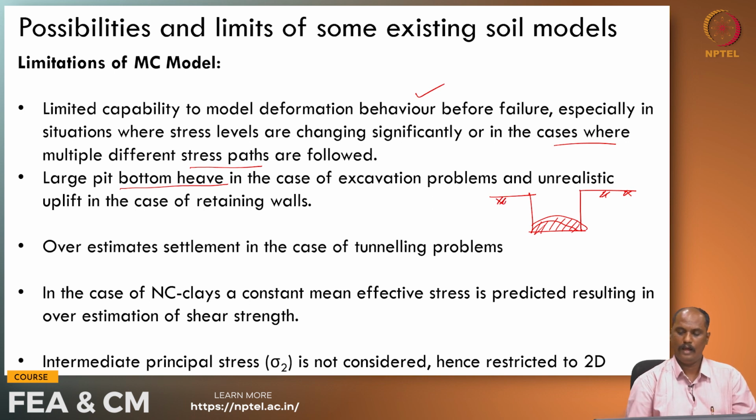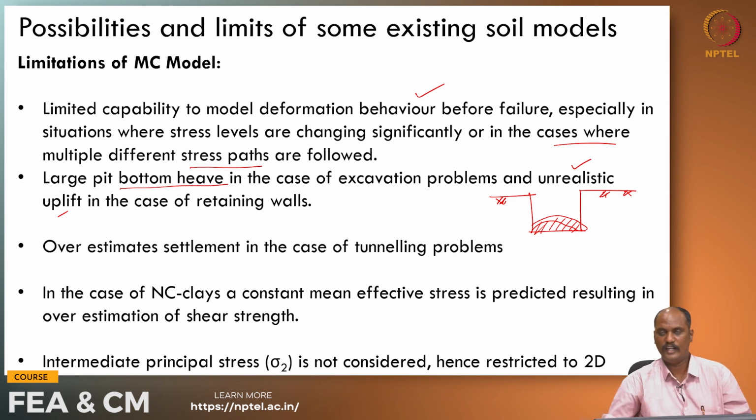You also encounter unrealistic uplift in the case of retaining walls. This is again a problem with the Mohr-Coulomb model. When it comes to tunneling problems, we have unusual, overestimated settlements. When it comes to normally consolidated clays, the very important aspect is that a constant mean effective stress is being predicted.